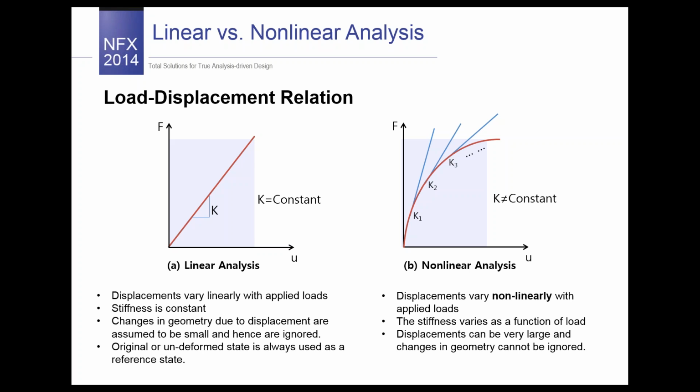So how is this definition related to the FEA? The best way is to look at the load displacement response of one or more characteristic load introduction points. If we take a look at the graph on the left, we see the structural response, which is deformation, and this deformation is linearly proportional to the magnitude of the load. Due to that, we know that the analysis of such a structure is known as linear analysis.